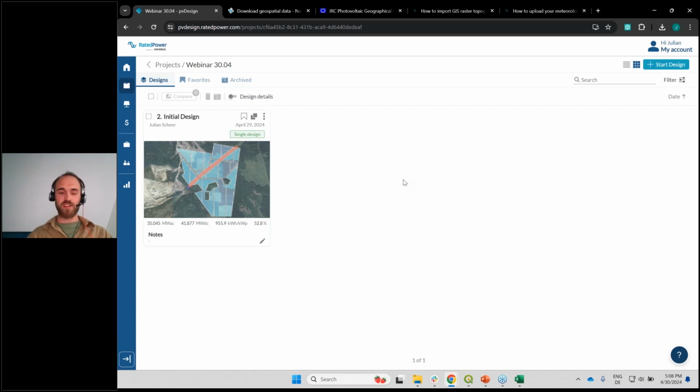And the challenge would be now, okay, do I have the exact cadastre data? Do I use the correct boundary layers? Did I make sure that any restriction zones like buildings are excluded? And also, did I make sure that any other transmission lines are respected as well? So these are the topics I had in mind when doing this layout.